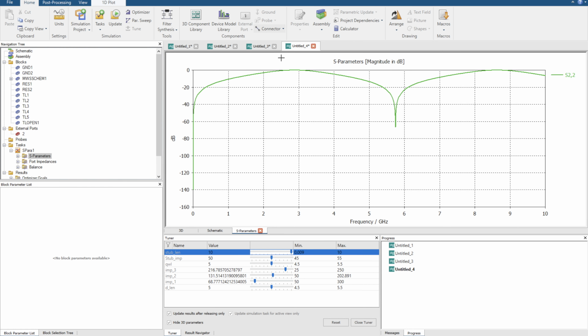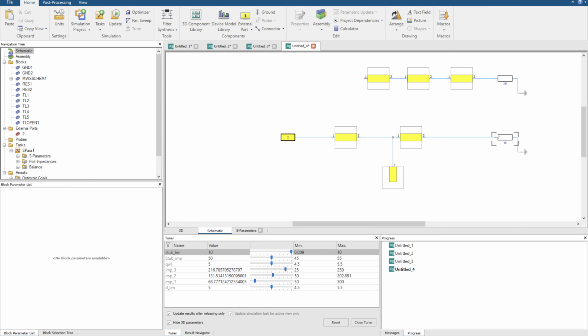So we find that at around 3 gigahertz, we've actually got no energy passing, or all the energy being reflected. So it's like a perfect stop filter. It's like, stop this frequency, I'm stopping it passing through. And if we really wanted to get rid of the load, let's just put another port. So now we can see the filtering effect we get from just a single stub.